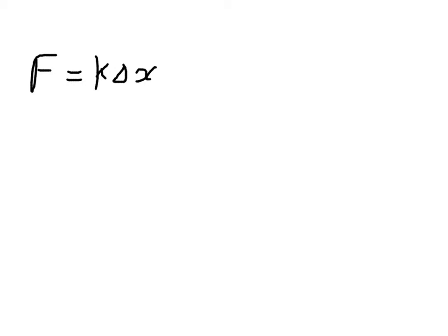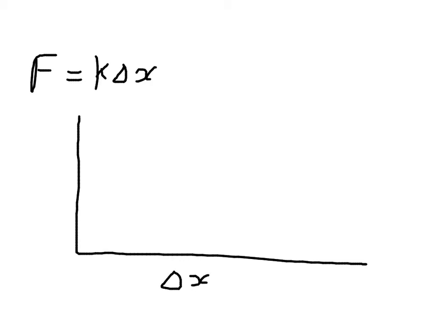If we jump on to slide 3 and look at that graph, I'll try and reproduce it. What we can say for materials is that, for an extension while you apply a force, there is a proportional region, a region of proportionality. That's your elastic region. There is a proportional bit, and then a little bit more where it's starting to curve that's still elastic. The point where the linear bit finishes is your proportional limit.